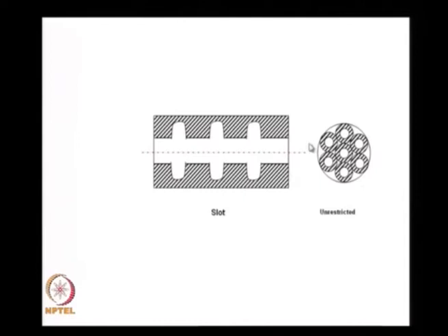If I put a number of these together and allow burning on the outer surface and here, stacked together in a case, I am having unrestricted burning, radially inward here, radially outward there, and therefore I get a large surface area. But then the problem is, how do I control the burning taking place?